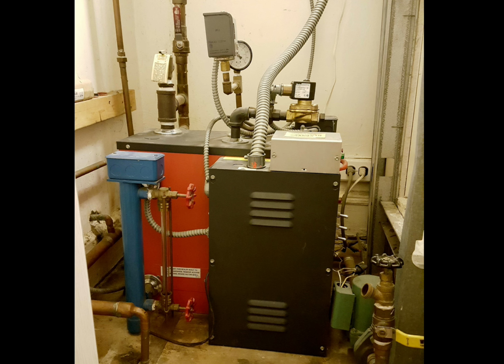And the pressure limit, the cutout of where I set this, was between 7.5 to 8 psi. I believe sometimes it even hit 8 psi. All right? So just keep that in mind. But there's another reason why I'm bringing it up in this particular scenario right now. Because what you see on this is a basic pressuretrol. And I believe I set the cut in to 5 psi. Cut out at 7.5, 8 psi, cut back in at 5. That's pretty much where I set it. 5 was more than enough. Some might say, well, you didn't need 7.5 to 8 psi. Why go with that one? Well, it was just a matter of me being greedy.